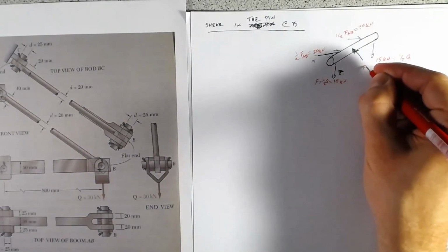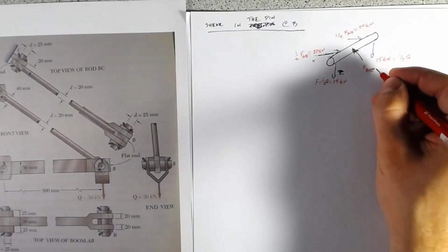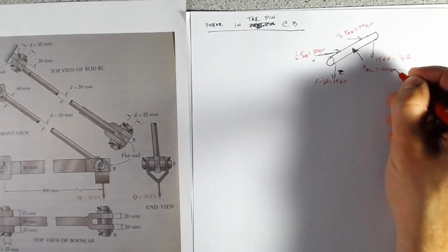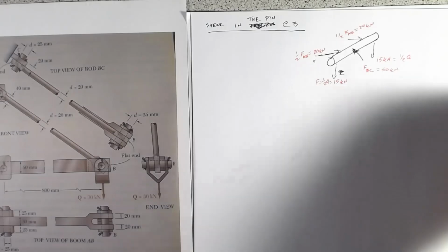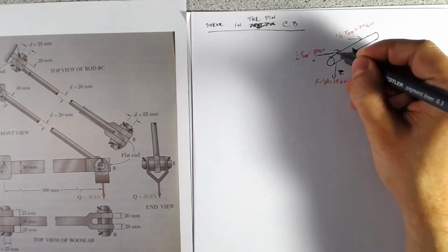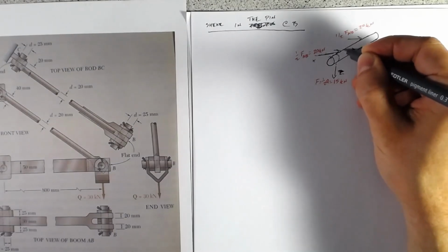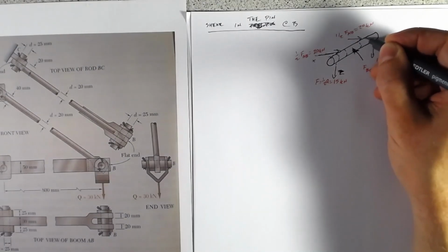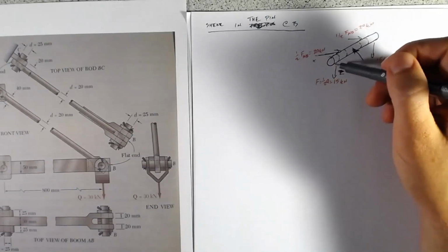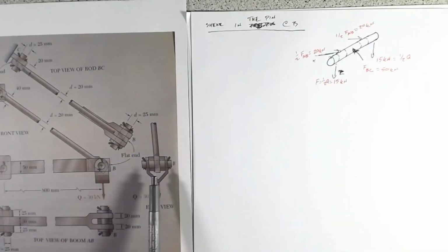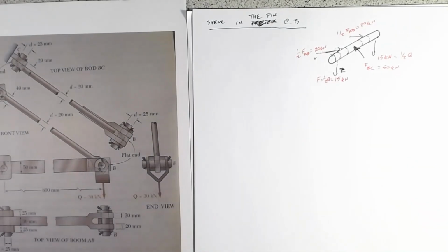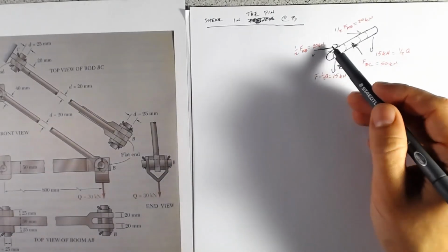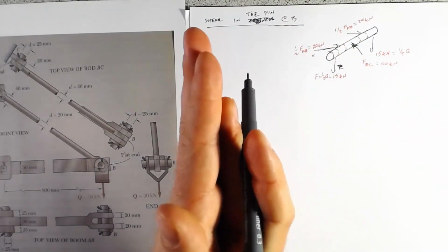And that's going to be the force BC, and that equals 50 kilonewtons. All right, so now that we've got the forces on there, let's break this down into different components. I like to think of it as slices with different loads on, similar to what you're seeing here with each of these plates. You can think of these slices as where those plates are acting, and that's the interface that's getting sheared.